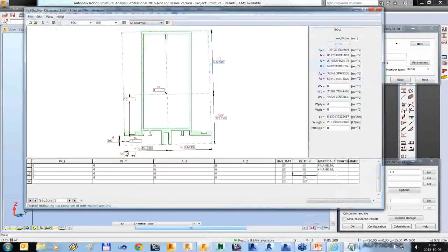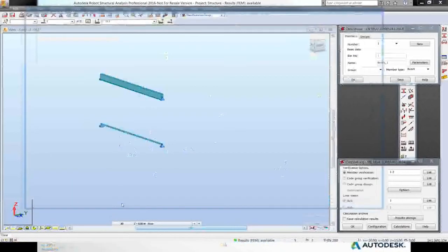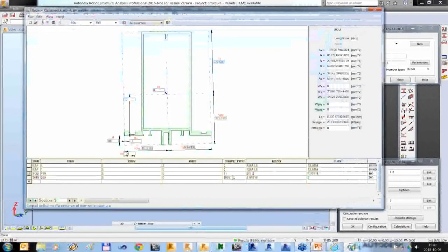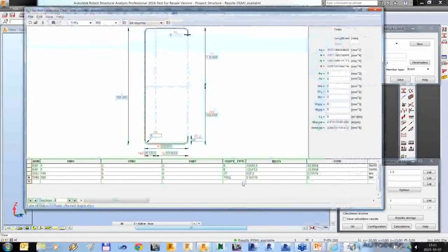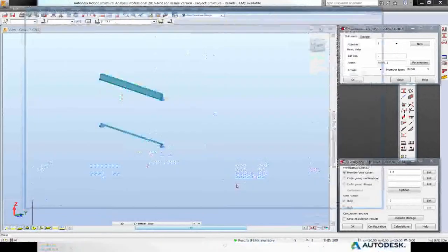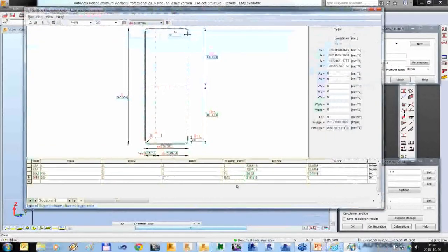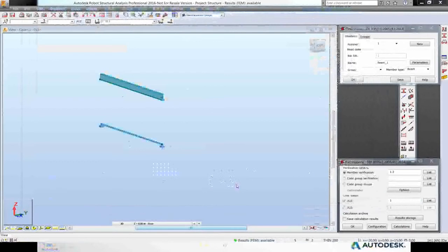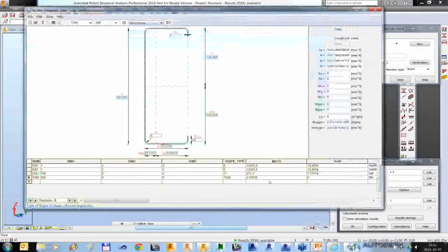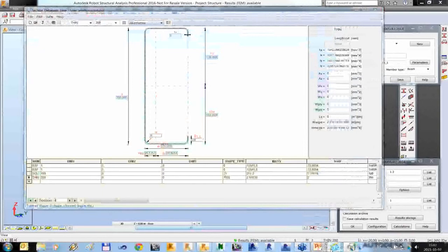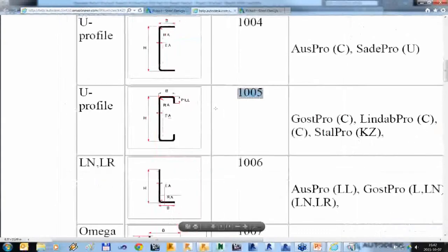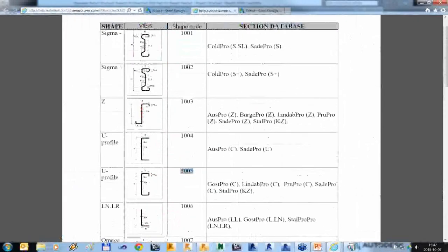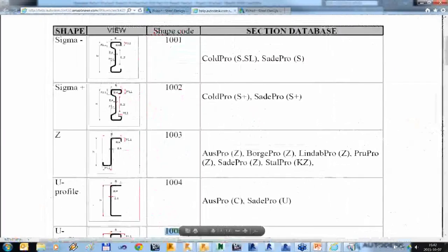But it does not force the program to properly recognize the part for steel design. Steel design is based on the section shape type numbers. So you have to additionally fill in the section shapes properly here, and then additional data if required. For some solid sections, you can fill in this data in the saving to database window. For fin-wall, basing on this document, you have to additionally fill some fields in the section database.